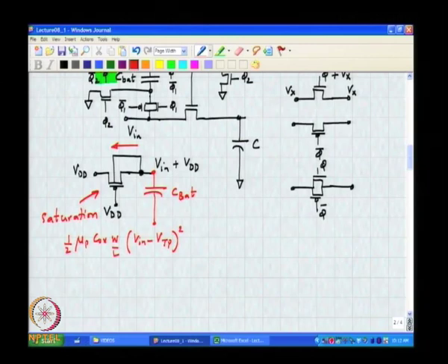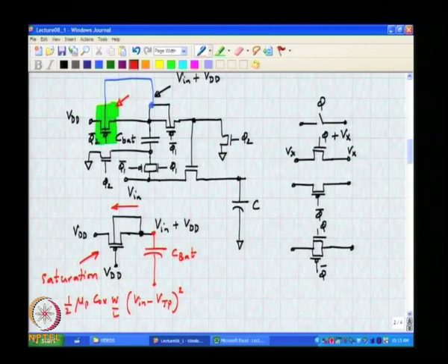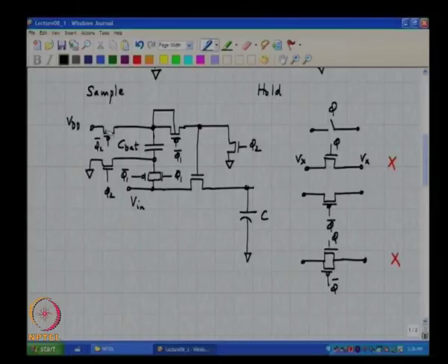And this is completely undesirable, because you want the battery to hold on to that voltage VDD without losing that voltage, and therefore, using a PMOS switch here is also not a permissible solution. So, we now need to figure out what to do, because it seems as if the various switches we know, namely the NMOS transistor, the PMOS transistor, or the pass gate, none of them are suitable for use in this situation.